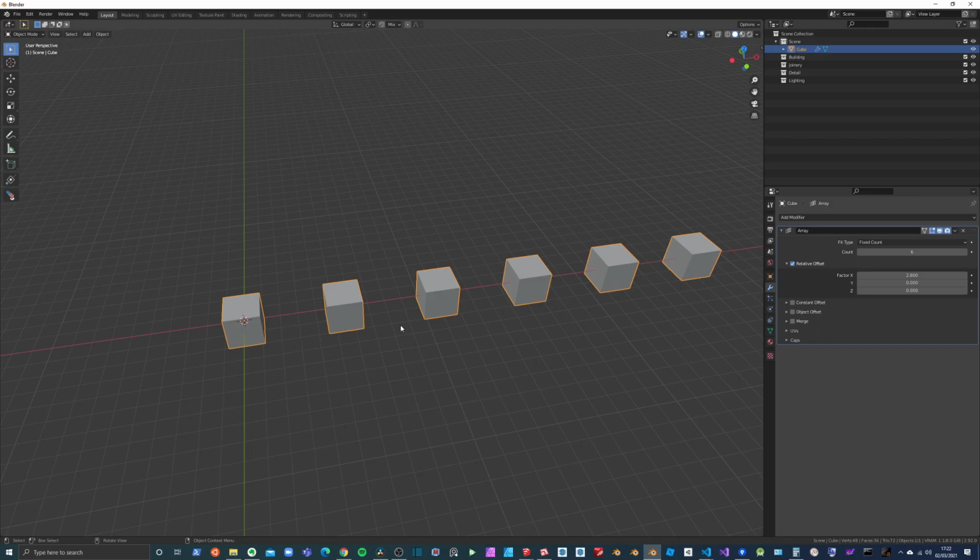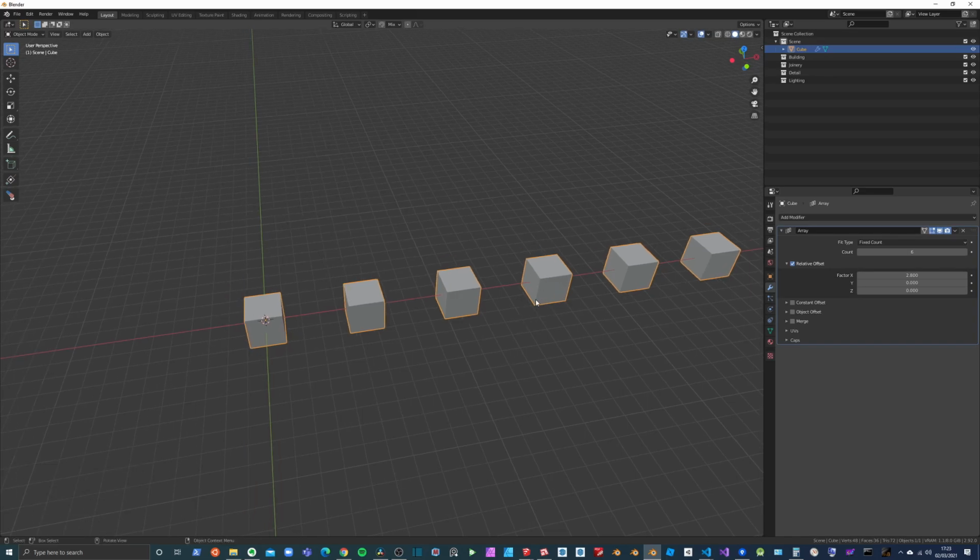However, in other pieces of software, maybe in things like SketchUp, you can simply grab the object, holding Control, move it to a location, and once you set that final location, you can either do something like ×3, and that will create 3 objects with that exact spacing that you've put there, or you can move the object much further away and hit the divide button, and it will divide that space and duplicate the objects within that space.